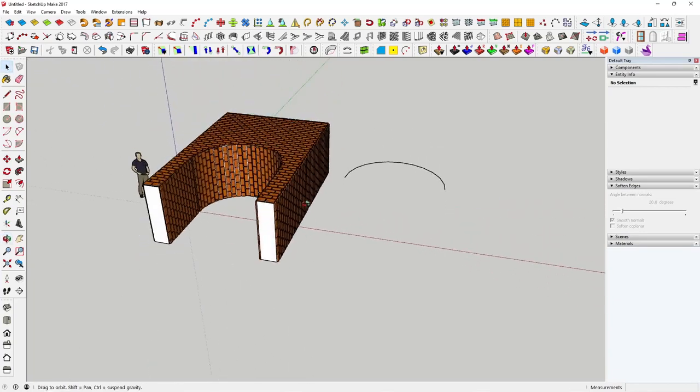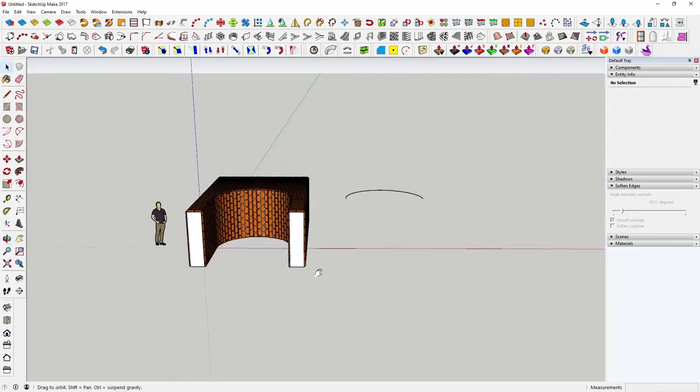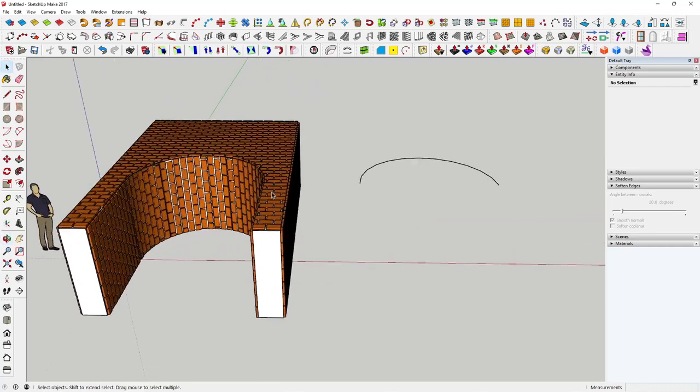I don't put bricks on the back because that's going on the bed of your printer. But for a better job, if you want it, say 25mm wide, in your slicer, cut this down to 12.5, duplicate it, 2 parts, glue it together.